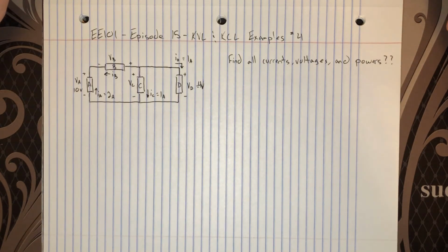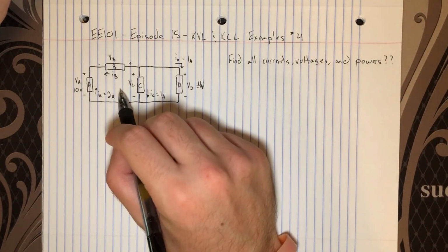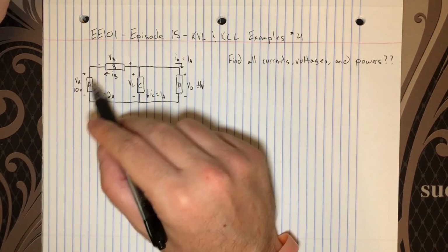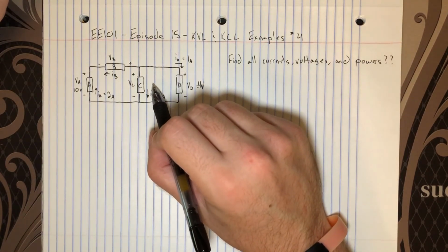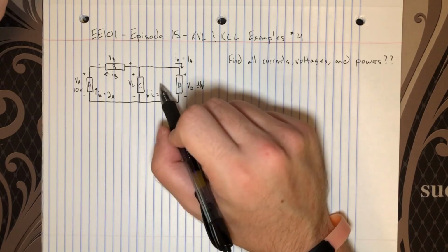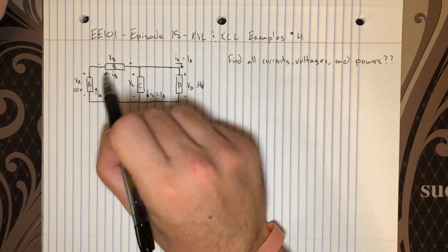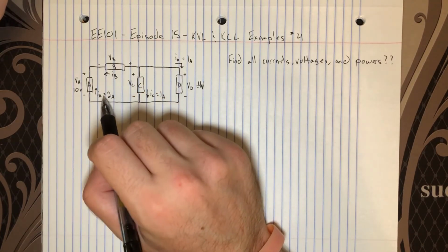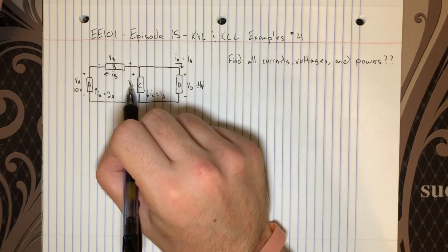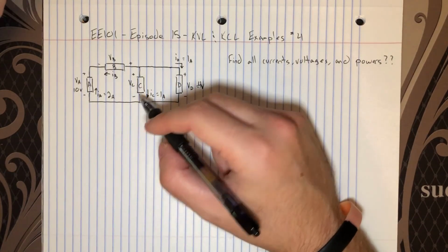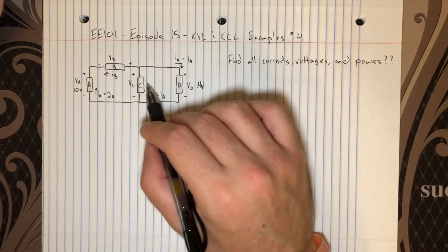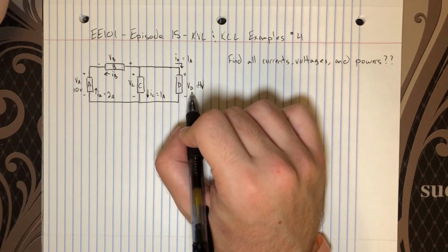The first thing to notice is that our options are to do a KVL around this loop with A, B, and C, or to do a KVL around this loop with C and D. The problem with ABC is we don't actually know VB, so doing a KVL analysis there won't tell us VC because we have 2 unknowns. But doing a KVL with C and D should work, because there are only 2 elements in this loop and we know the voltage across the other element.